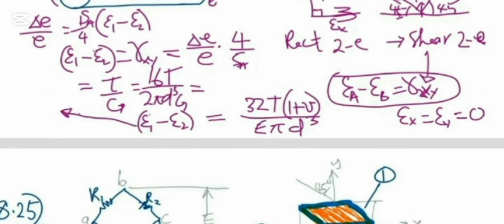Remember that this arrangement also has temperature compensation, whereby if there is error due to temperature from the tensile gauge, let's assume the increase due to temperature from the tensile one is going to cancel with, it's going to be neutralized by that from the effect of the compressive. So the effect of the error due to temperature will cancel out to become equal to 0.